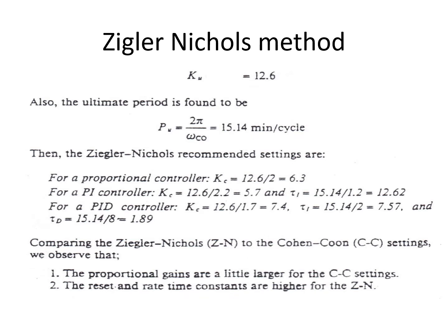If you use the Ziegler-Nichols method on the same system, and get the continuous oscillation, you're going to get the Ku of 12.6. Ultimate period, you will get about 15.14 minutes. Either you can calculate using a formula or use the frequency response technique. Later they will show you. Or what you can get again straight from the graph, you can get 15.14.